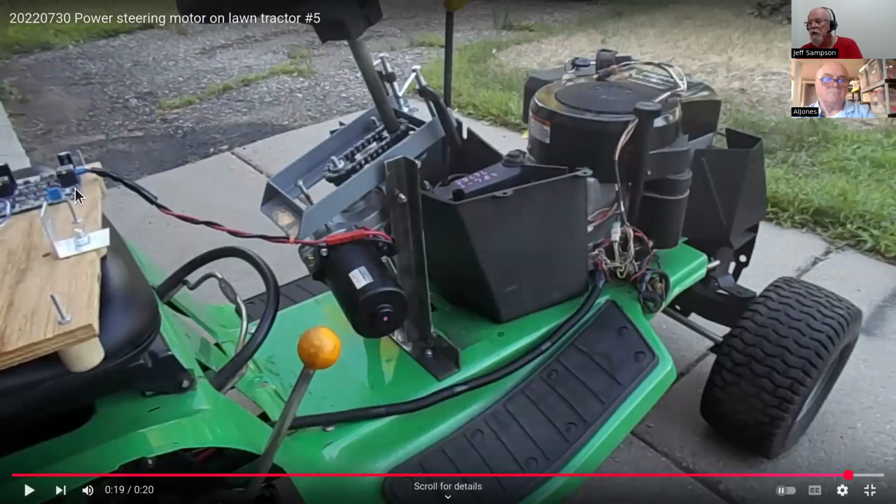So apparently the frequency this board is generating, this is all built right into that driver board, apparently the frequency it's generating is above the level of human hearing. So definitely if you run 20 kHz, you can't hear it. And you can drop it down, maybe get down to 10 kHz. It'd be starting to be a little bit annoying. And kids and dogs are gonna say, hey, what's that noise? But old people can't hear that noise.